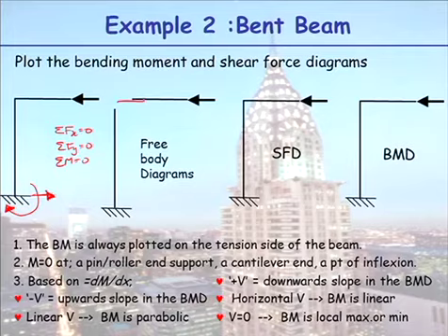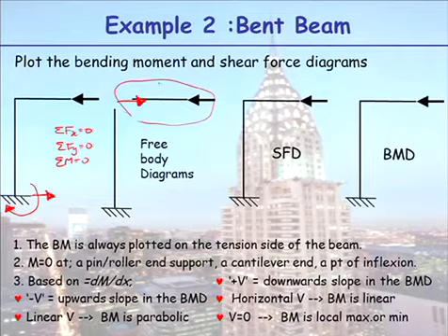I can draw it up here now as two free body diagrams. The force is to the left. If I draw my unknown shear, axial and moment, I'll have no shear in this free body diagram system, no moment, just a horizontal. Now when I draw, remember at an internal pin, when its force is in one direction, you draw it equal and opposite. That means I would draw that force to the left. And when I consider my vertical free body diagram, that means I must have a force to the right. And again, those two forces are creating a couple going anti-clockwise. So that moment must go clockwise.